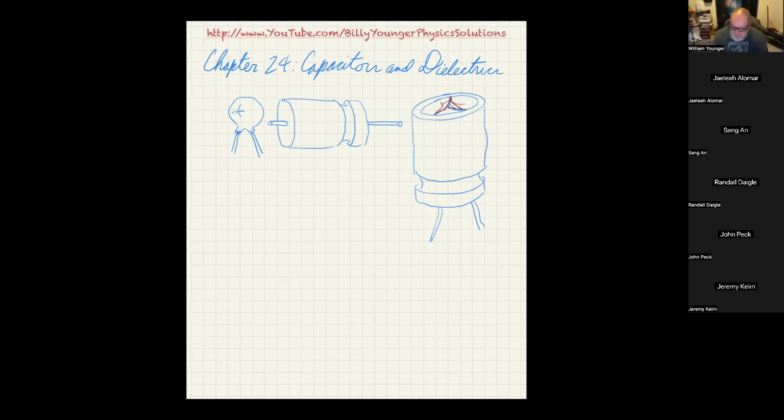So that actually happens. I've been lucky enough to find things that I needed to fix, and I open them up and I see one of the capacitors is like that. All I've got to do is find out what the capacitance and the power and temperature ratings are, because they are designed to withstand certain temperatures and certain powers as well. So you've got to look up that kind of stuff. But generally, the thing about capacitors that matters is the capacitance.